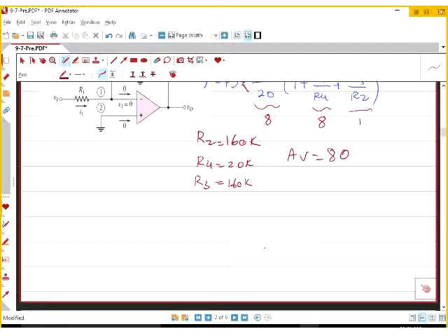If I design the circuit with those values, hopefully I get 75 in the lab. So for the gain, always shoot for a little bit higher. Don't shoot for 200. You don't need that gain. That's going to saturate the next stage and cause problems. A little bit higher is fine. There are some other parameters, as we go through the course, where you need to think, okay, I don't want this to be that high, I'm going to shoot for lower.